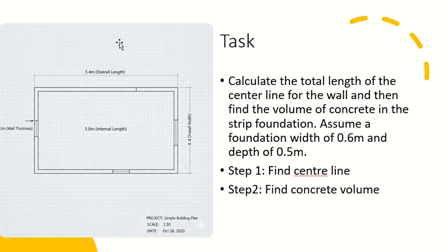It's the same, right? Now, what is this? Footing width of, okay. So now we have a footing. We have a trench footing around this room or plot or whatever you call it. So we'll find out the center line, and using the length of the center line, we calculate the quantity of concrete. So you already have internal girth or external girth, whichever one you want to use. So tell me the quantities. First of all, what is the length of the center line? Tell me.